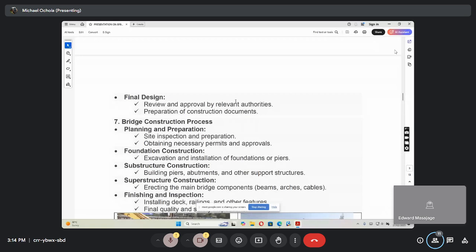That's why when you're looking at an existing bridge and you see certain parts already rusted, like steel, that means there's already section loss. As a designer, you get worried. People will just say, no, the bridge works. But you as a designer say, if this area was 20 millimeters square, and now with corrosion it could be 15, it means the load designed for 20 millimeters square no longer works at this stage. So you begin to relate your design knowledge and construction knowledge to help you manage inspection and maintenance of bridges.